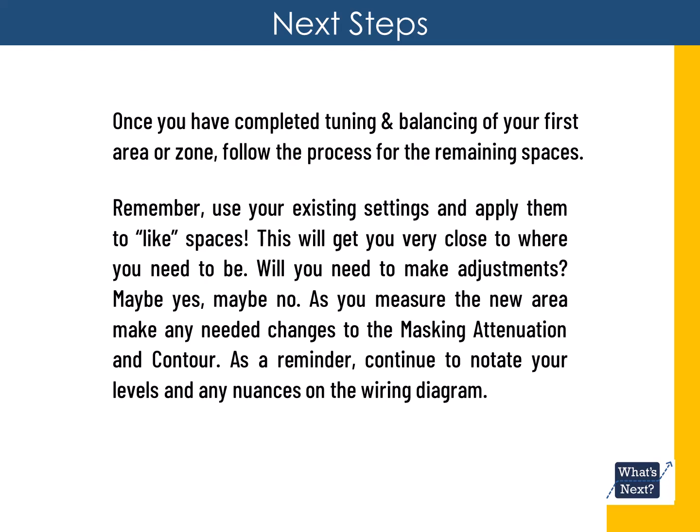Okay, once you have completed tuning and balancing of your first area or zone, follow that process for the remaining spaces. Remember, use your existing settings and apply them to like spaces. Just tuned an open area? Those settings will very likely get you close to where you need to be in additional open areas. Will you need to make adjustments? Maybe yes, maybe no. As you measure the new area, make any needed changes to the masking attenuation and contour. As a reminder, continue to notate your levels and any nuances on the wiring diagram.